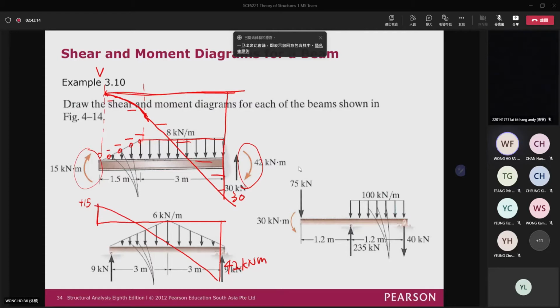Well, for the other one, actually, it is quite similar. You can see that for this one, this triangle simply supports the beam. So here it is negative value, 0, negative, and more negative. And then it is still negative, but it becomes smaller and smaller and becomes 0, right? So this is the change of the shear force along the beam.